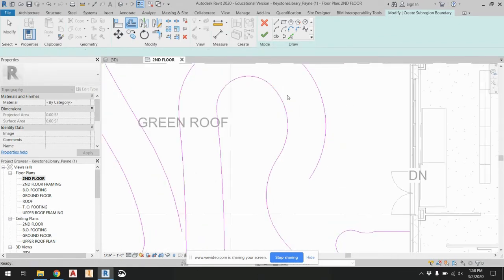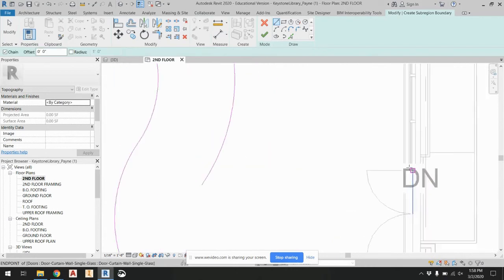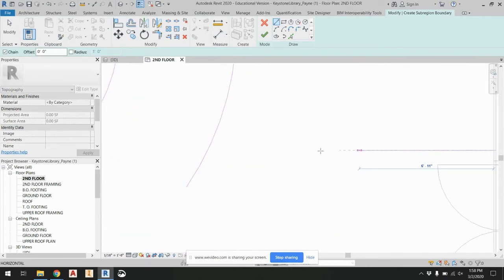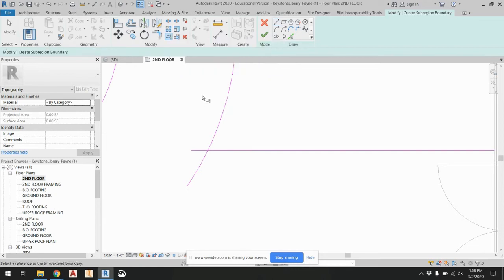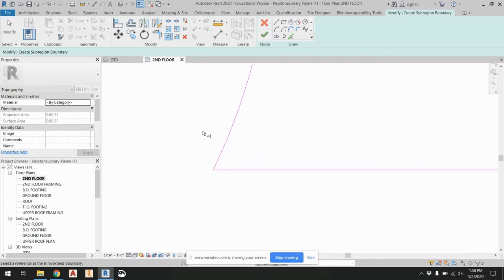All right. And then to finish it off here, just do that. And then you can do a trim command right here. So the way you use trim is you select the item you want to be your boundary. So like I'm gonna cut this. I cut it based on this boundary. This is the boundary I want to cut on. Then you click on the part you keep. This is the cutting boundary. I want to remove this. This is the part I keep. All right.